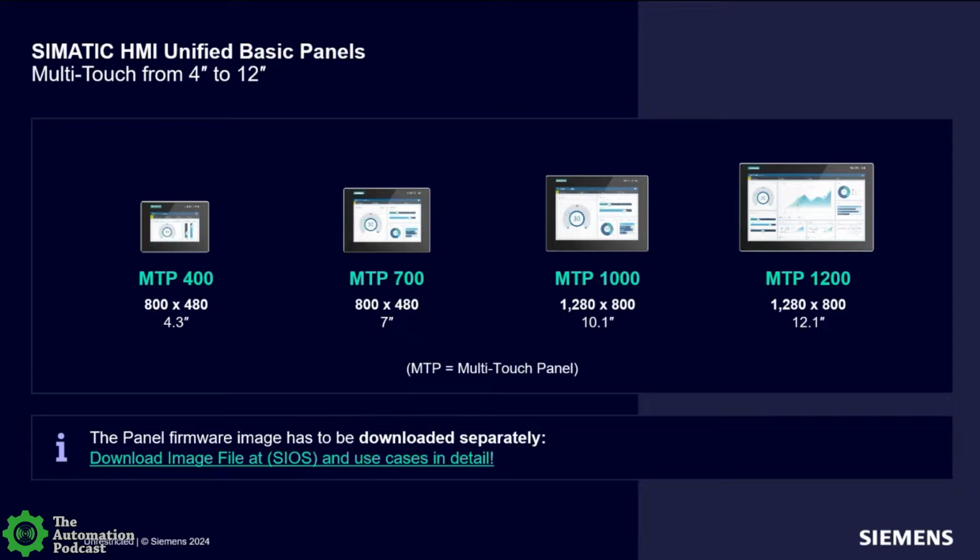It'll say, I can't download to this because you've potentially engineered a functional feature set that this piece of hardware that I'm connected to doesn't know how to interpret. So you need to update the image. They call it either image or operating system of the panel. You need to do that first and then download the project. And it would wipe the project off of the whole panel.